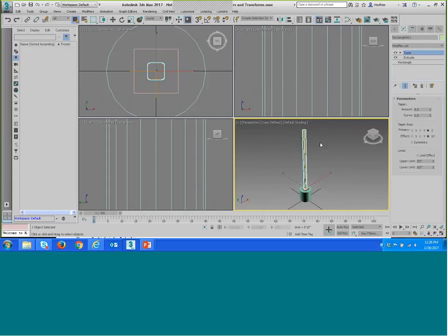So what we can do, and you can notice that here the taper modifier is the next in line, so you can still access the parameters of the extrude modifier or the rectangle shape. You can access all those parameters and modify them. But right now we will taper it at the topmost position, and we can do that by giving an amount of 0.5.